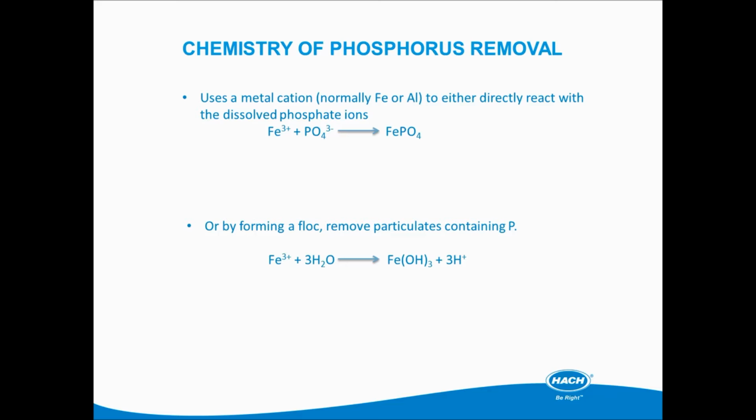For example, in aqueous solutions between pHs 7 and 8, ferric phosphate solubility is between 0.2 and 0.15 milligrams per litre respectively, and we'll come back to this figure later. If we were just dealing with a solution containing only soluble orthophosphate, that would be the end of the story. But the consent is for total phosphorus, so the particulate loading has to be dealt with.